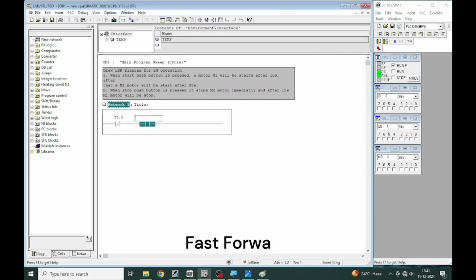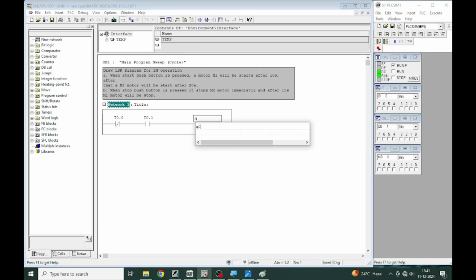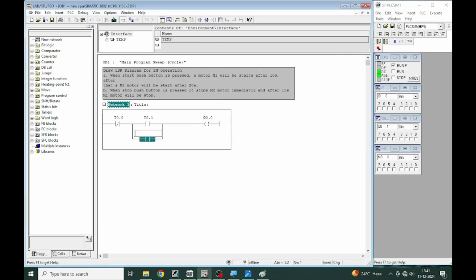In the previous video I talked about memory bit. Here you can see why we use memory bit instead of output bit. For latching I am using an output bit. Later I will take the contacts of this address. Let's see. Turn on I0.0 and you see this Q0.0 address is continuously in a high state, and we can't use this Q0.0 anymore as a physical address.